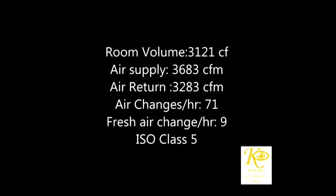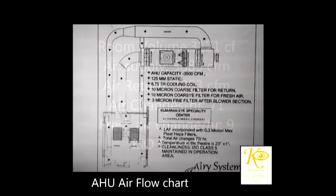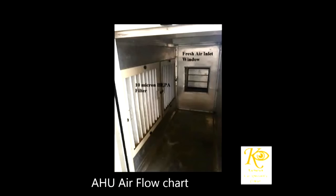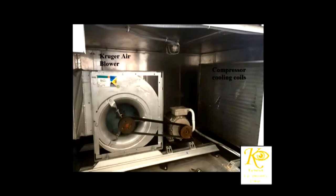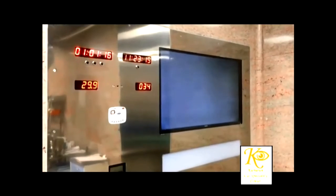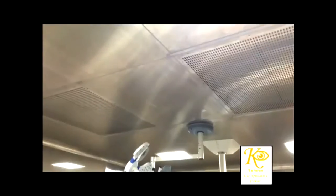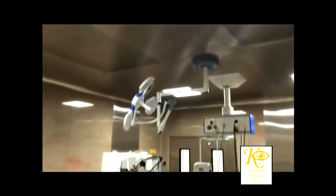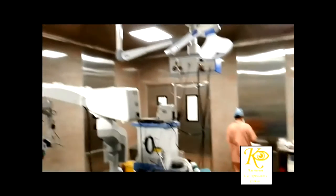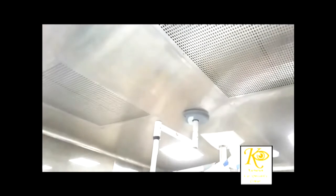This is a small video which shows the working pattern of the HVAC system. This is the flow chart as I showed you before. The air enters these filters in the air handling unit. It is cooled and blown with pressure through the 3 micron filter to finally enter the laminar airflow system inside the theater. The parameters are constantly monitored. The only thing to take care of is that the hood of the table should be placed right under the laminar airflow system.